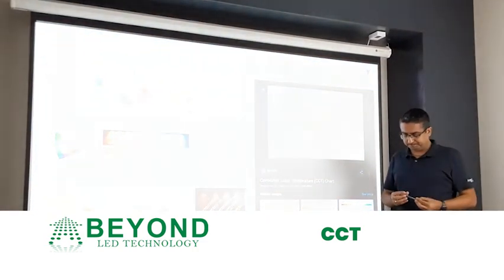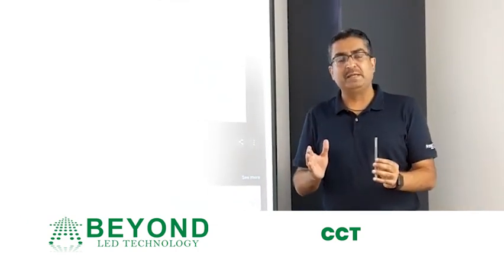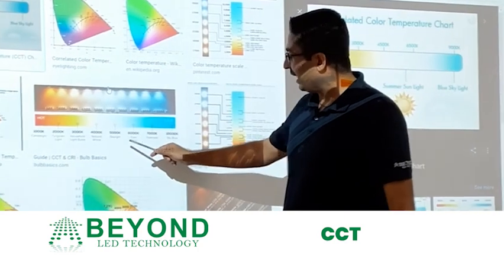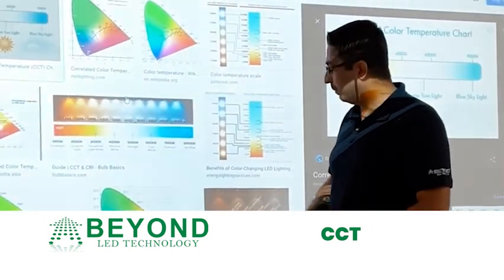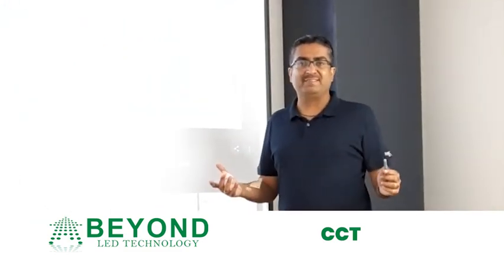In order to be qualified for DLC and Energy Star indoor lighting, the product has to be 5000K or less than 5000K. So if the color temperature of a light is 4000, 3000, or 2700K, it's no problem. Anything higher than 5000K in the indoor lighting category cannot be DLC or Energy Star.